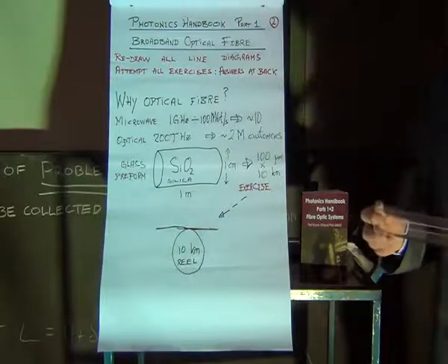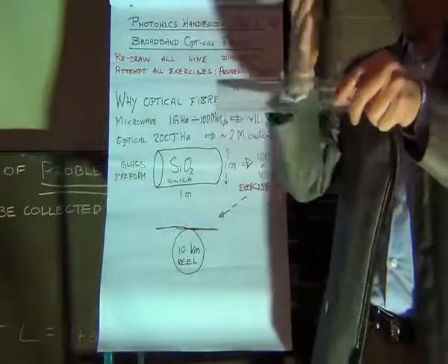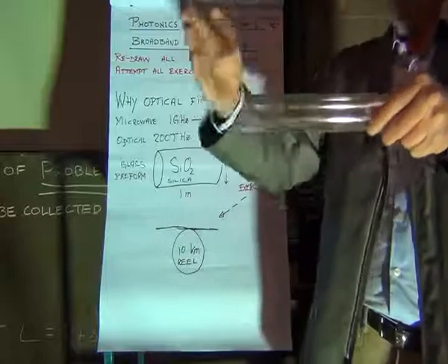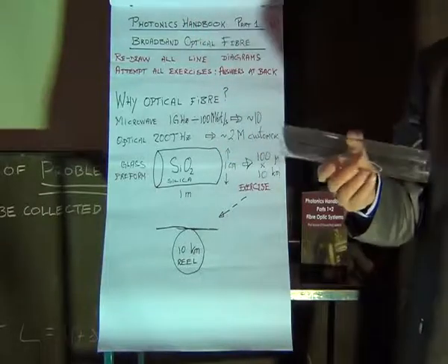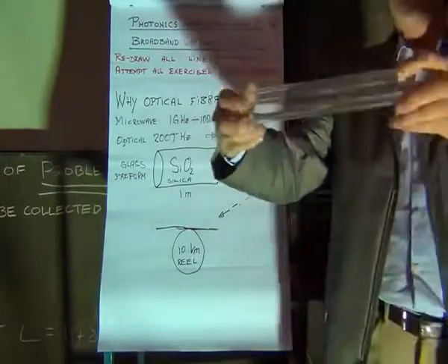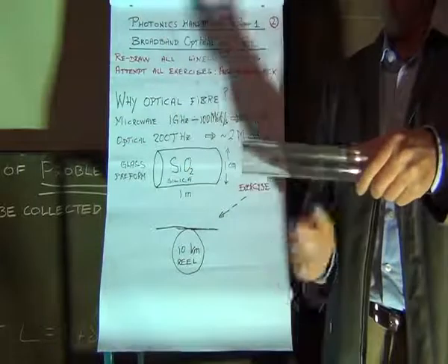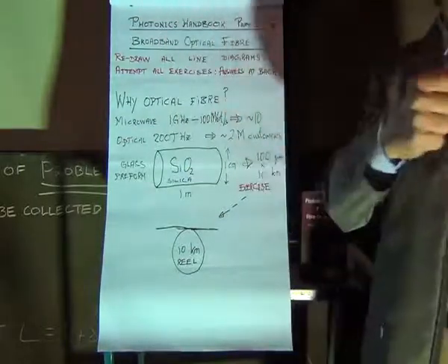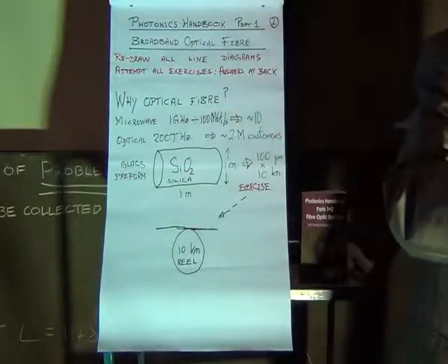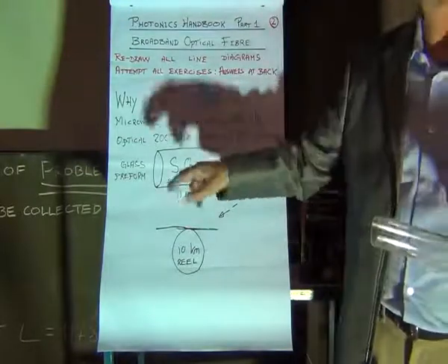So Bell Labs are famous for developments in this area, but also places like the University of Southampton and other places. We inject carrier gases into this, and meanwhile we keep the whole thing hot with a flame, and they found it convenient to use a conventional lathe in the beginning. So this was mounted on a lathe and rotated. The gases were injected, the whole thing was kept hot, and by chemical vapor deposition, as with growing silicon chips, you deposit the silicate inside.